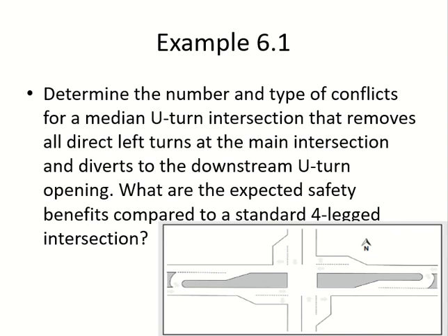Okay, they are both coming from the same lane. Okay, so it's a diverge. Okay, and then this guy will go in this direction, okay. And there could be another guy which is coming from here. I made two conflict points. Crossing and merge. Okay, so this is how you make the conflict points.